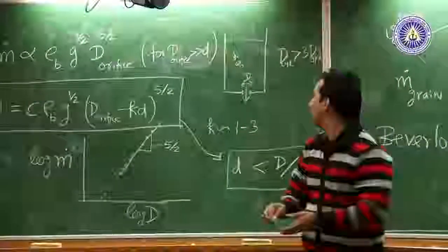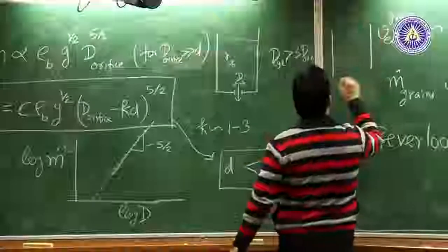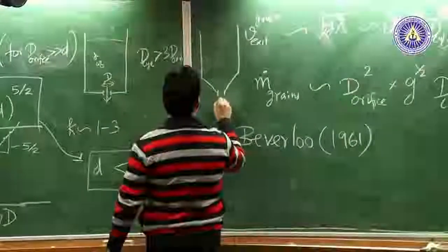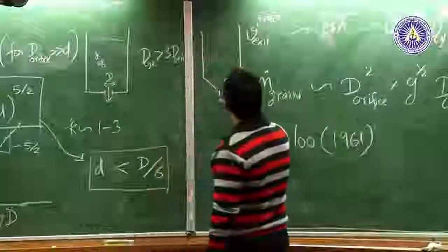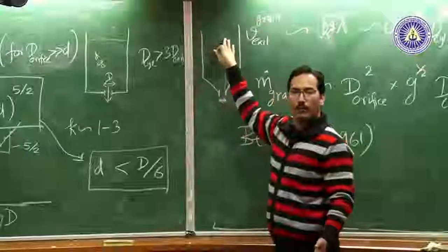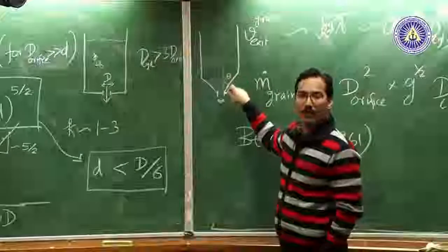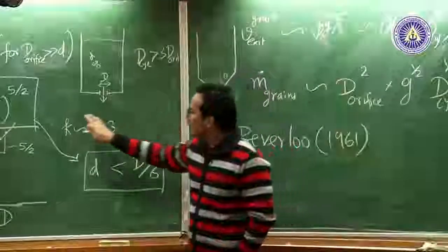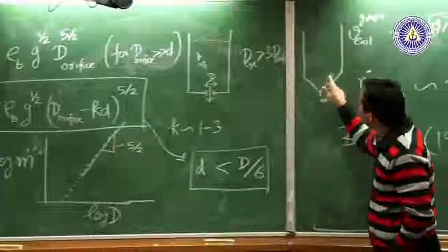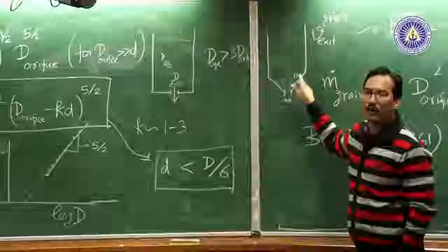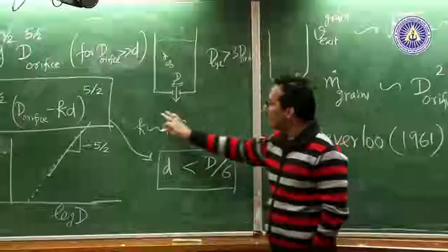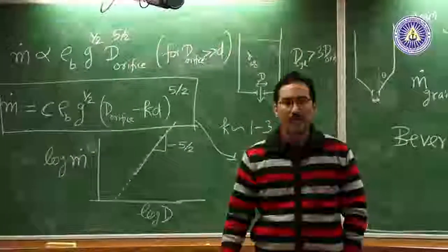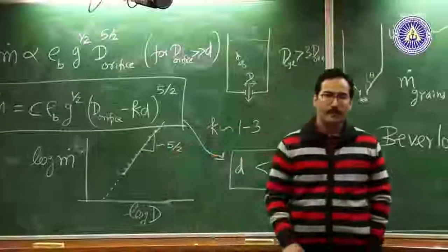Typically when you have flow occurring through a hopper, you can have something like this, and then the hopper diameter is, let's say, D. You will have some dependence on the material property, and the half angle of the hopper in that case. All that happens is you get a correction factor because of the material, the hopper angle, and other properties. But the essential form remains this, and that is why this is the most commonly cited, commonly used result.